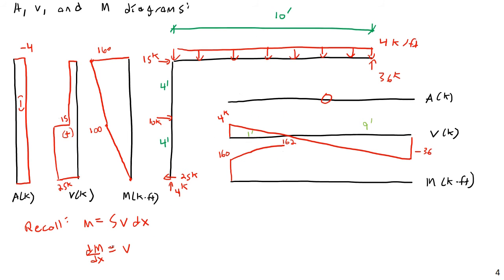Yes, we know the shear, again, is the slope of the moment function, so the slope should be decreasing as you go along. Then here, we know the slope is going to be getting increasingly negative, and the area of this, 1/2 base times height, when the height is -36 and the base is 9, you will get a value of -162, which means this thing is going to drop right back down to 0, and it's going to do so parabolically, with an increasingly negative slope. And this ends up having positive bending throughout. Nice, positive, happy bending. Think positive.